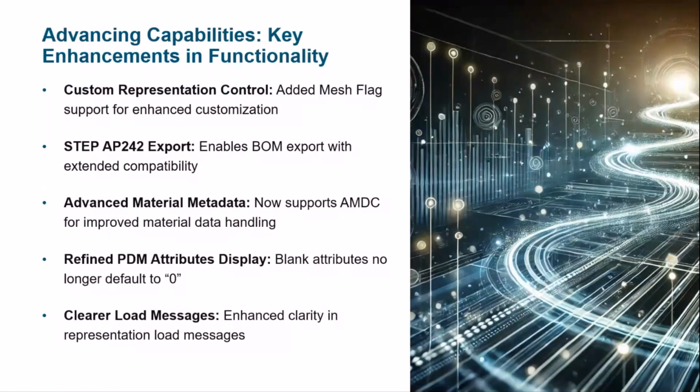This is all about the libraries, the team library, and the big framework change that we have done in HyperMesh 2025. Other than that, we have also done additional enhancements and a lot of bug fixes, and we'll look at some of the key advancements here. First and foremost that comes to mind is custom representation control. Custom representation control was missing mesh flag support. We have added that so that you can also create custom representations in one click in the representation create workflow.